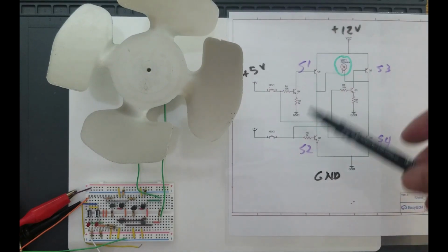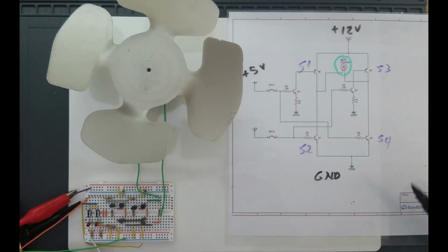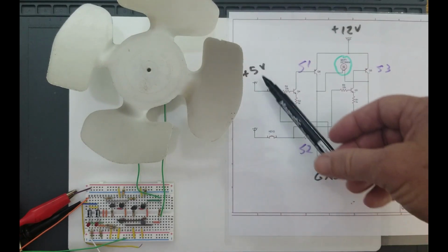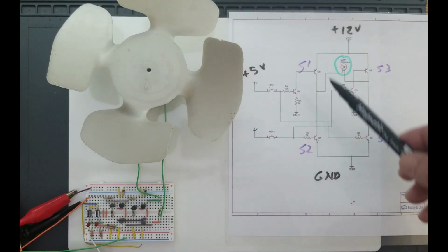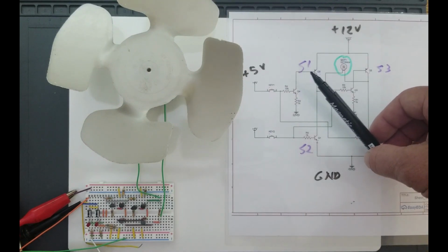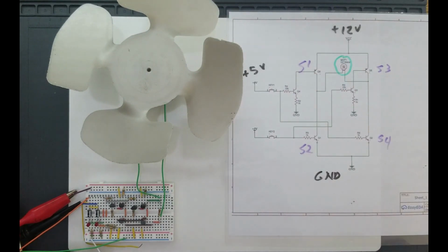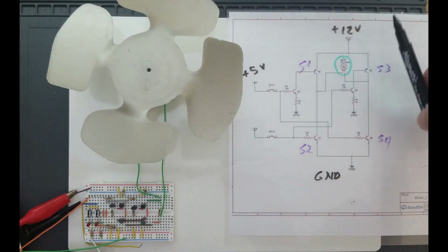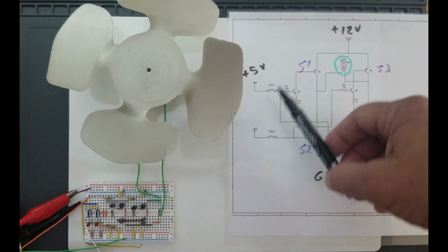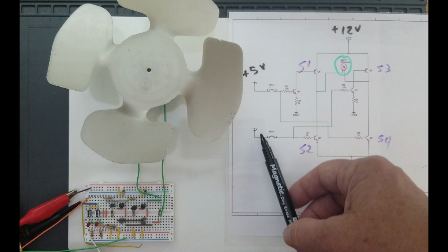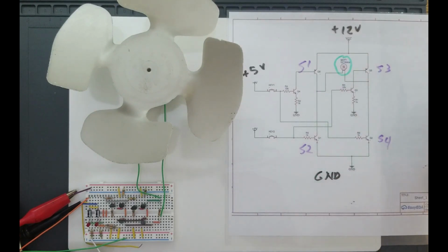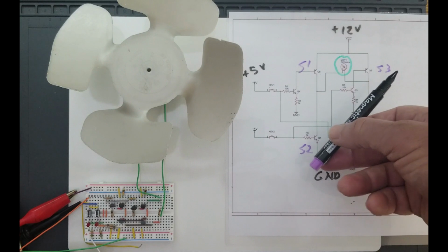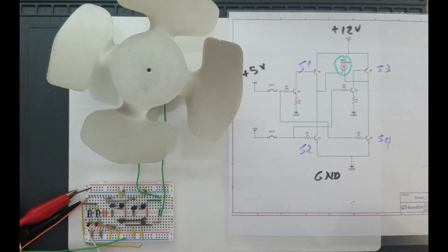So in reality, most H-bridges on control boards are going to be in IC form, but this shows how that is implemented internally, and as well how the relatively low voltage and current of a microcontroller output can, in effect, control loads with much higher voltages and currents. So with this 5-volt signal here, I can turn this transistor on, enable switches S1 and S4, and with this signal here, with the logic high of the microcontroller, 5 volts, I can enable switches S2 and S3, effectively reversing the polarity to the load.